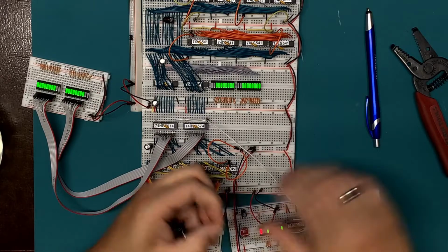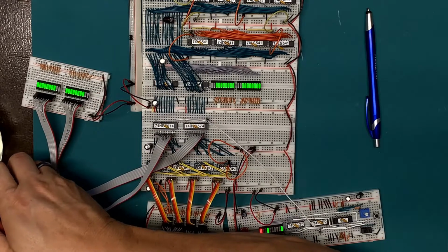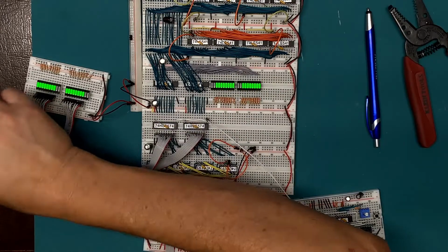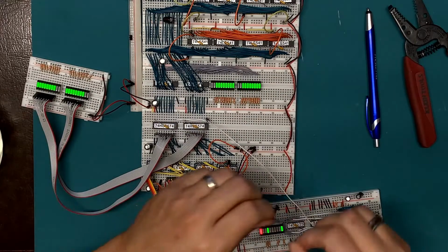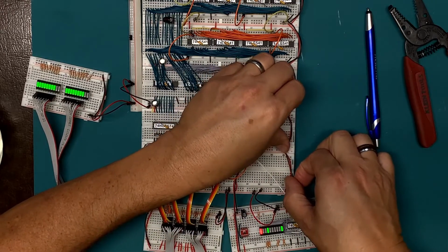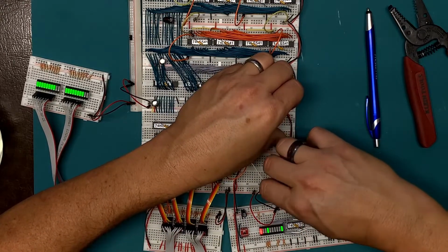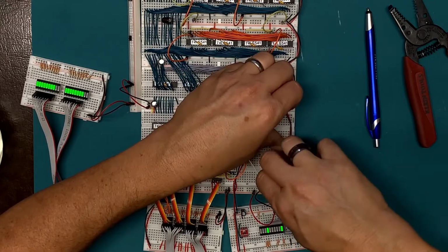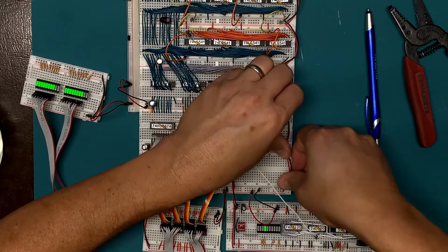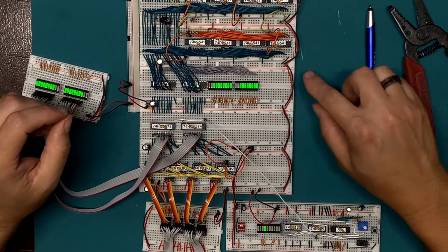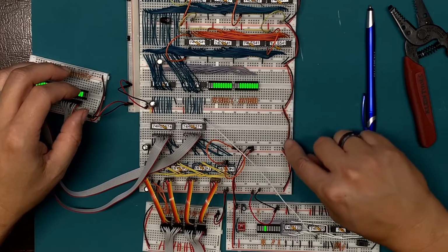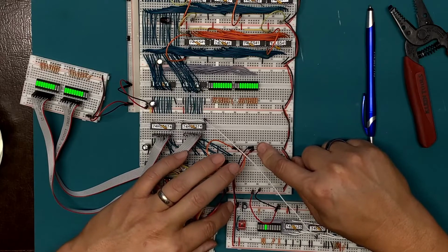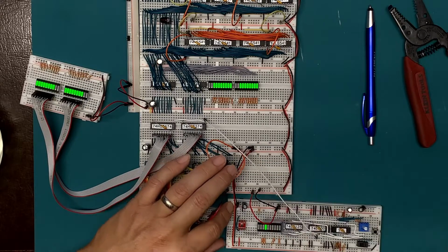It comes on at 4.63 volts and stays on until the power returns back up to 4.83 volts. And then there's whatever additional time from this capacitor, and I can see that it's gone out now as I get this ground hooked up. So what I have now is power coming all the way down to this rail. Power is coming from here into this, and then from here into this.